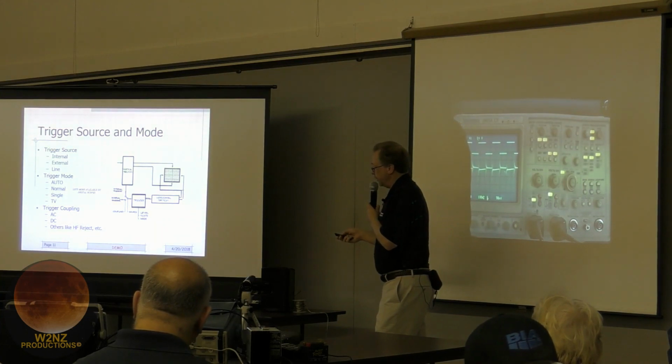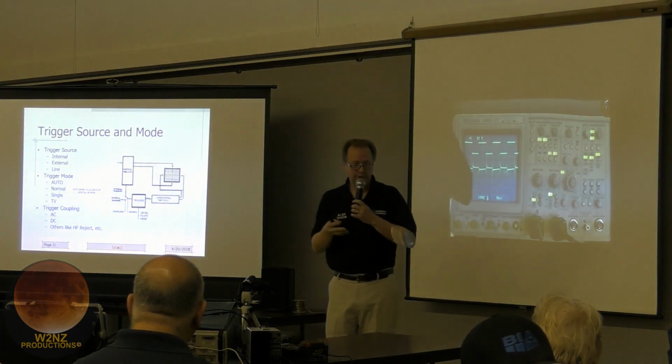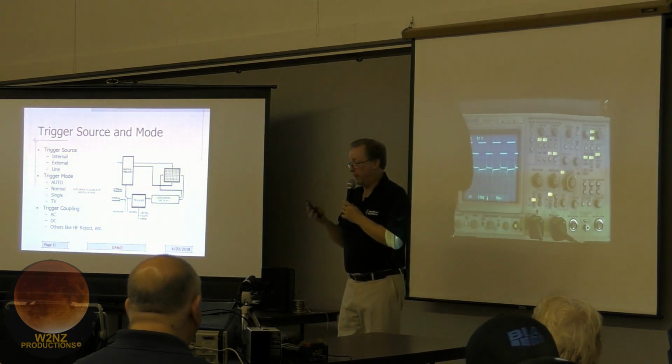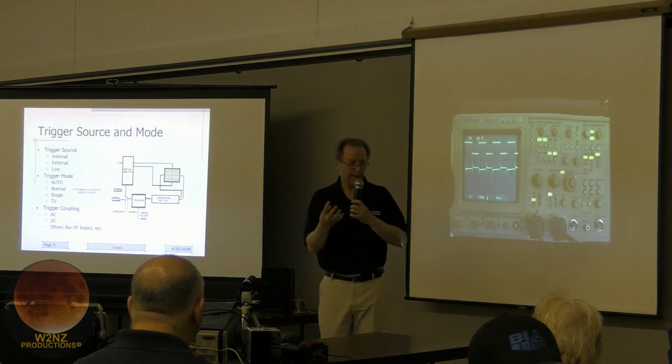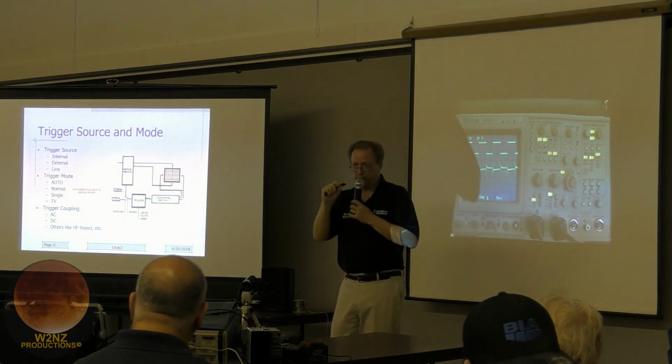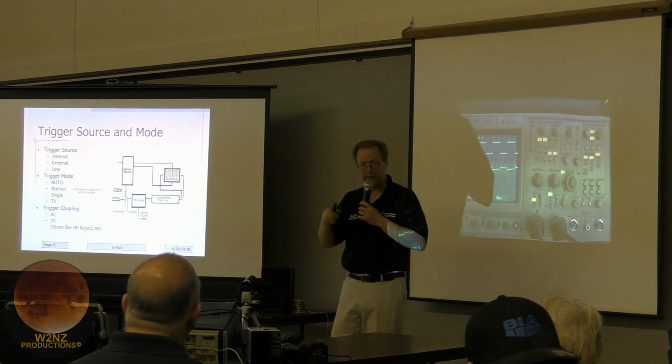There's also a line trigger, and that basically triggers on the line voltage, 60 hertz. So if you're looking at something like power supply hum, that's going to be synchronous to the 60 hertz line voltage, and it's a very small voltage, it might be tough to trigger on, switch to line trigger, and then you can actually go look at it.